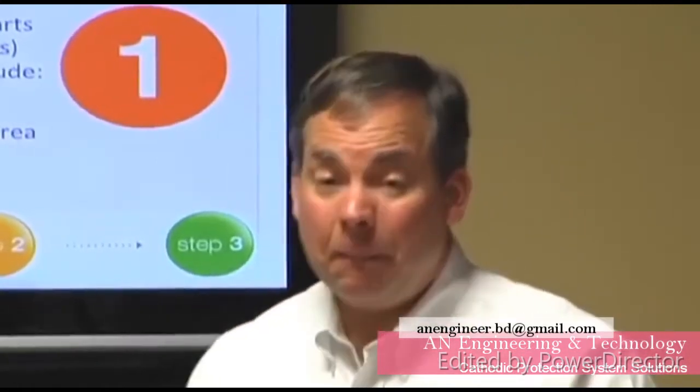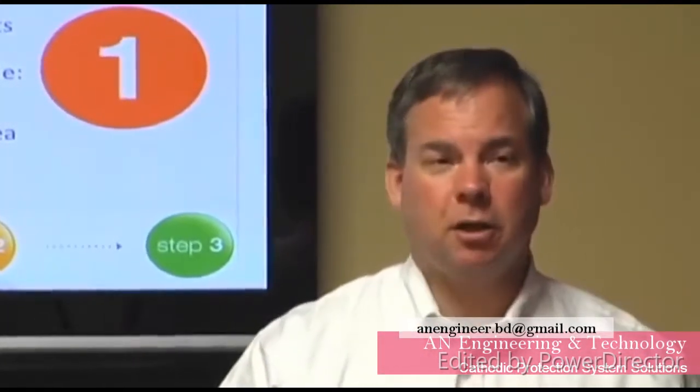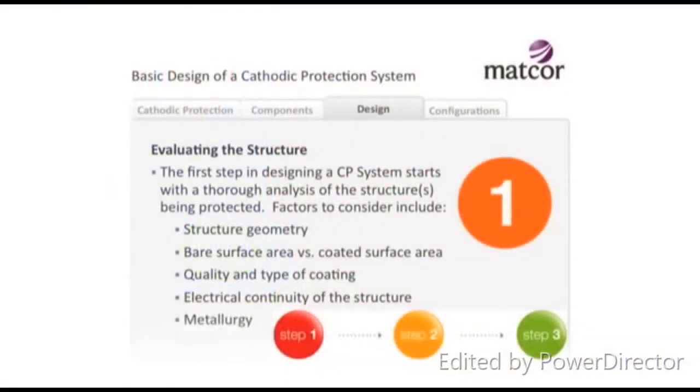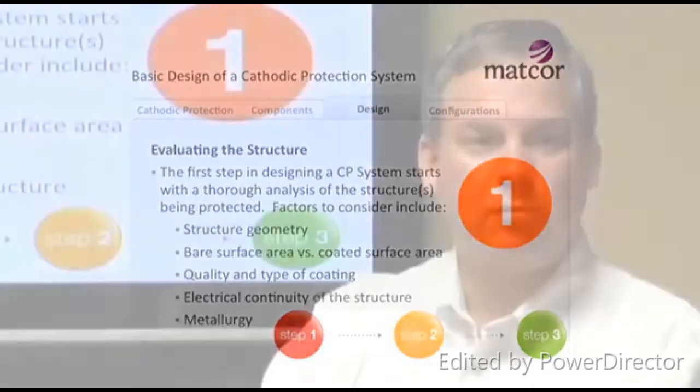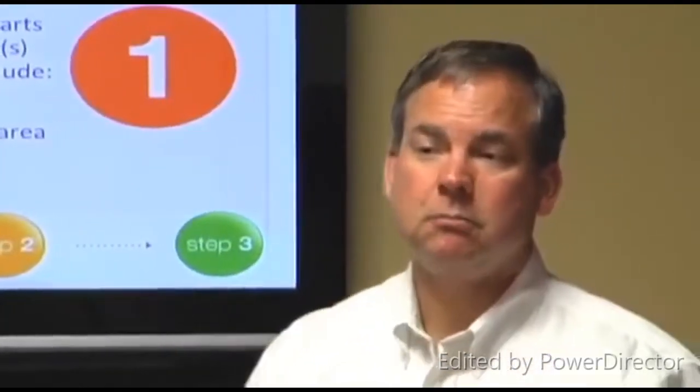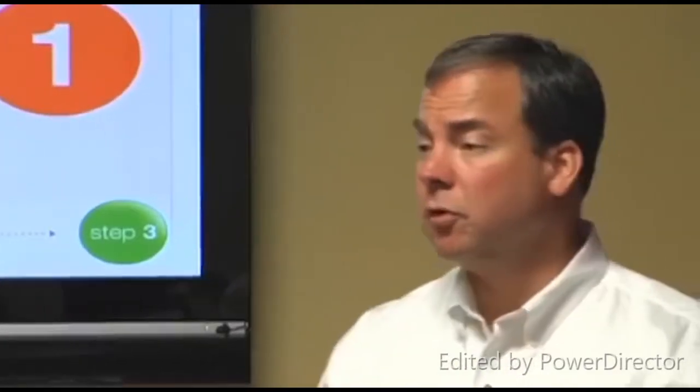That can be a really bad issue when you start putting cathodic protection on it, because what happens is you polarize one segment, but current's not flowing to the segment that's isolated because it's not part of the circuit. Now all of a sudden you have a major opportunity for current to flow off of your CP system onto the structure that's isolated and then back off again because it has to get back to the circuit, and where it goes back off you can have corrosion. We call that interference, and you can actually cause corrosion very quickly if you do that.